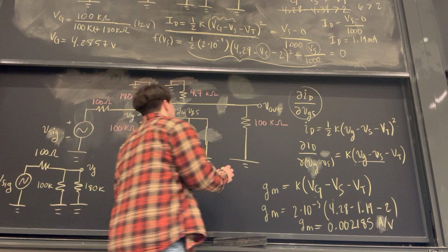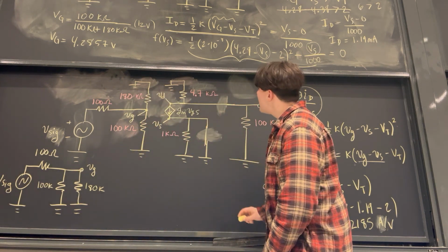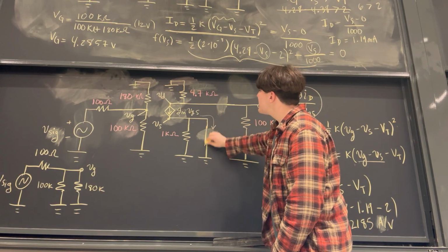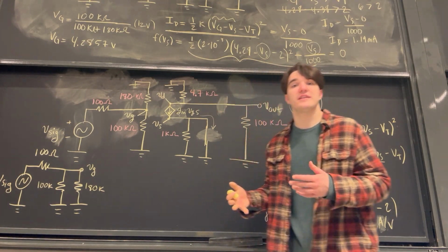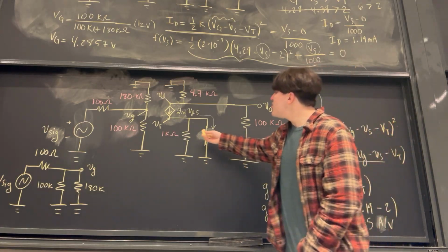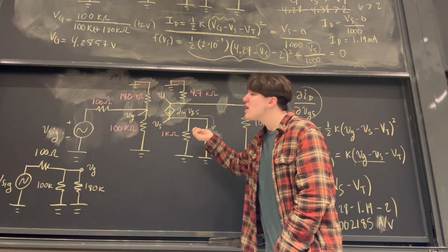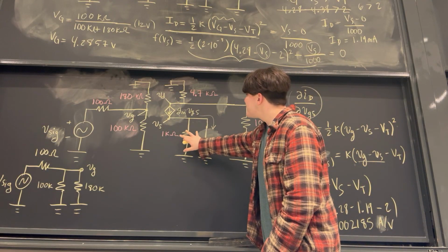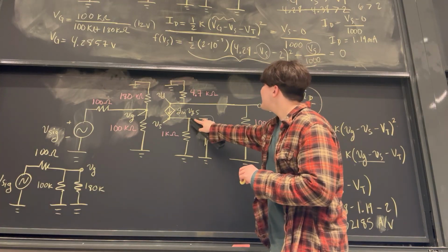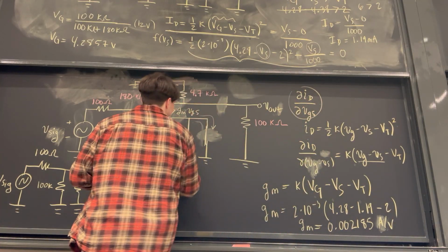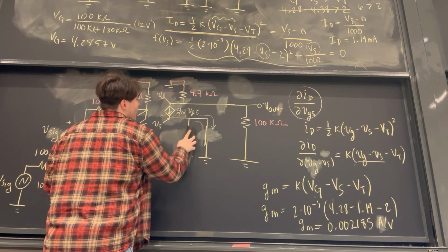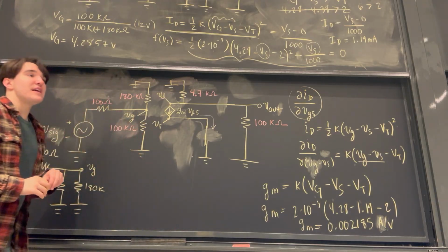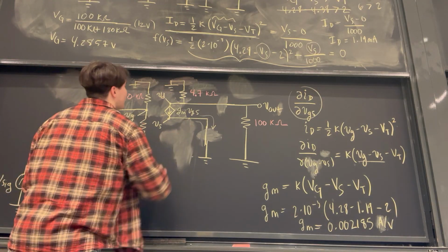And then also, let's notice, because this is a short circuit, no current flowing here will always flow through here because there's literally no resistance. It's perfect. Current will flow where there is zero resistance always. And no current will choose to flow through this path, which contains 1,000 ohms of resistance. So we've literally shorted this resistor out of the picture, because by providing this zero resistance path here, we've gotten rid of this resistor. No current will ever flow through it because it will always take the easier route. So it literally doesn't matter. It's a dead branch of the circuit. So we can get rid of that.